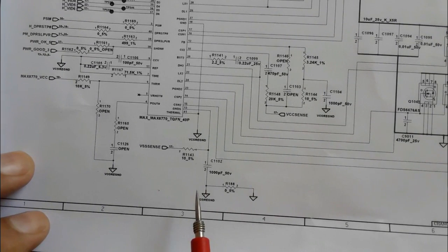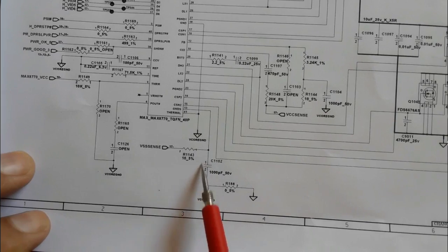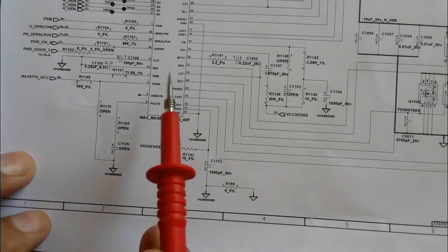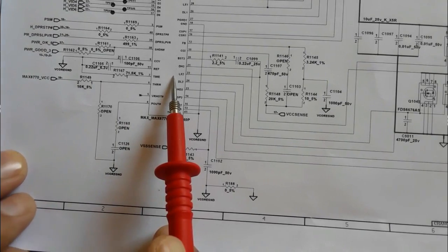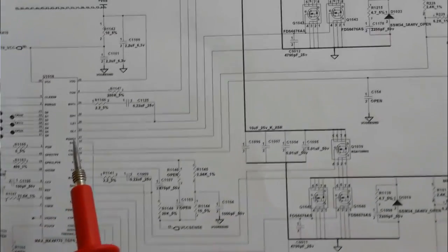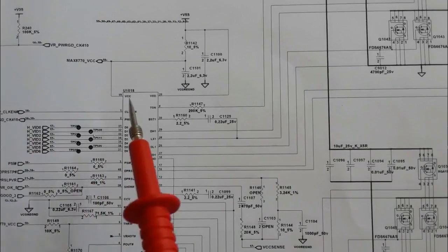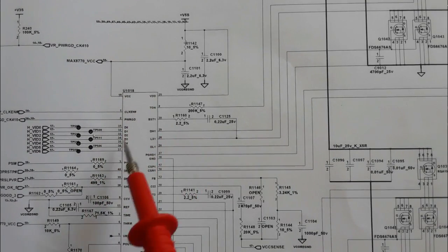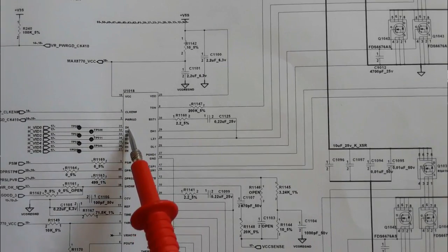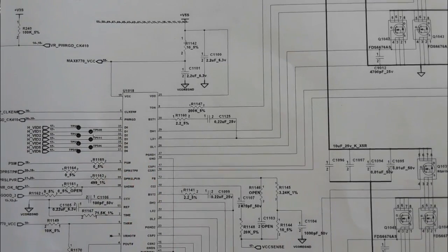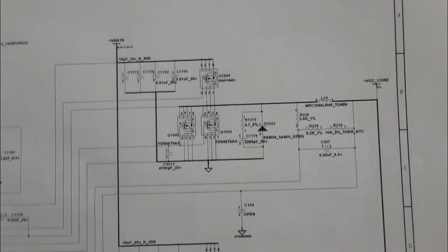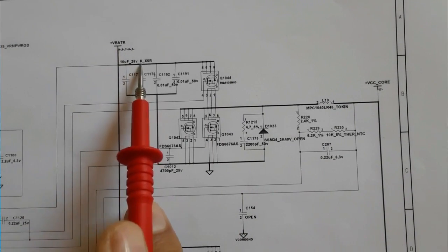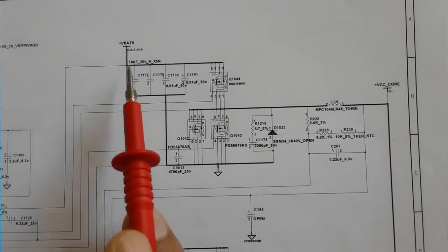So this is a technique that you can use to determine whether the power management IC is good or not. Just check the continuity between the terminals of a ceramic capacitor. If you find any shorted capacitor, it means the power management IC is bad. And of course you can check the presence of the input signals like VCC, VDD, etc. So you should also check the VBAT, the 19 volt, if it is present or not.